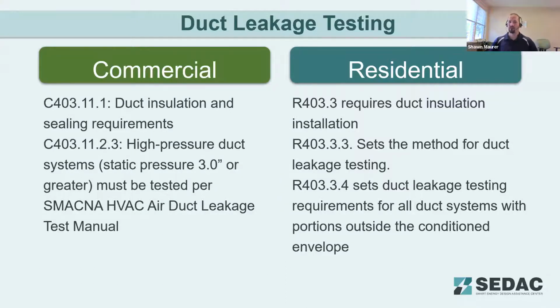If you're at 1 inch or 2 inch static pressure, then testing isn't required, but you do still have to do the sealing requirements, and that does need to be verified by the building official. And they'll probably do spot checks to look at that.